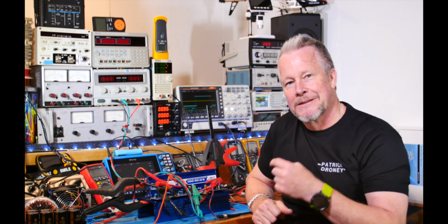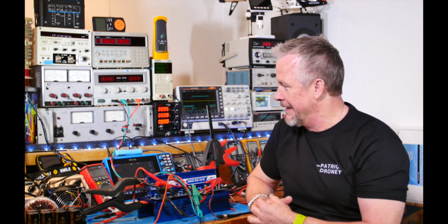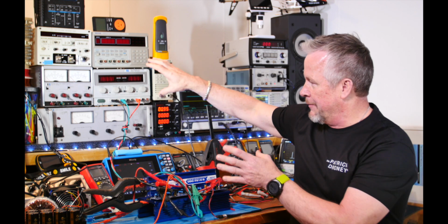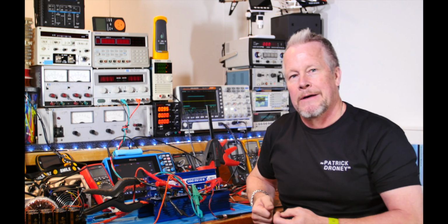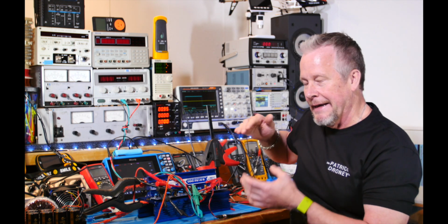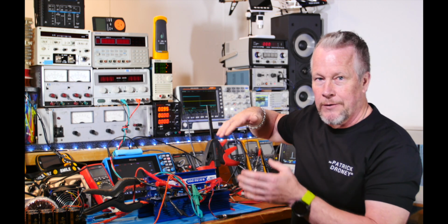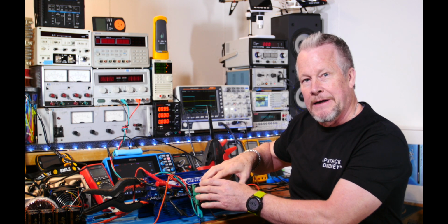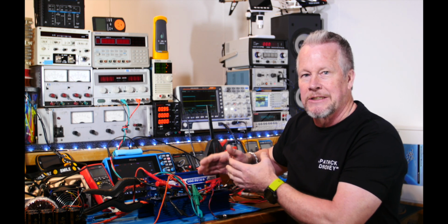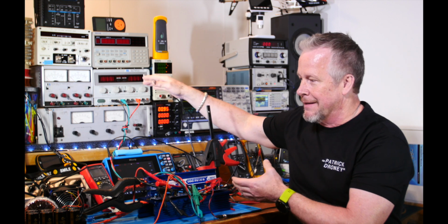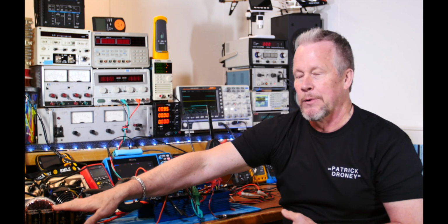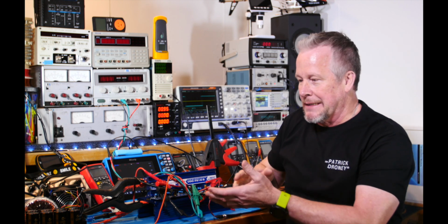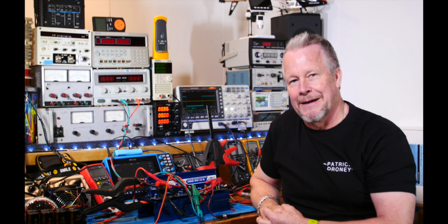So, alright, let's jump over here and I'll show you. We'll look at the FFT on the mixed signal scope, and we'll look at the current and the voltage ripple on the power supply, and the interplay when we adjust the signal level and increase it. We can see how increasing the current here, which you would think would help, actually doesn't, because of the lack of bulk capacitance that we will get in our real power supply but don't have here. So we're going to have to wait to optimize it later, is what it comes down to. But come over here and let's take a look.